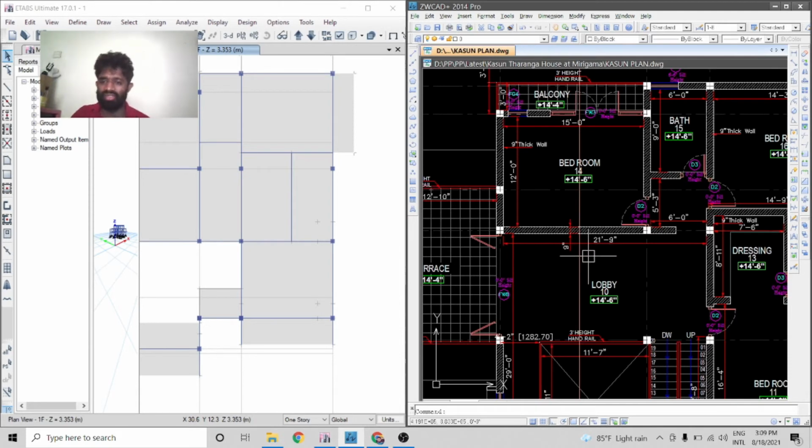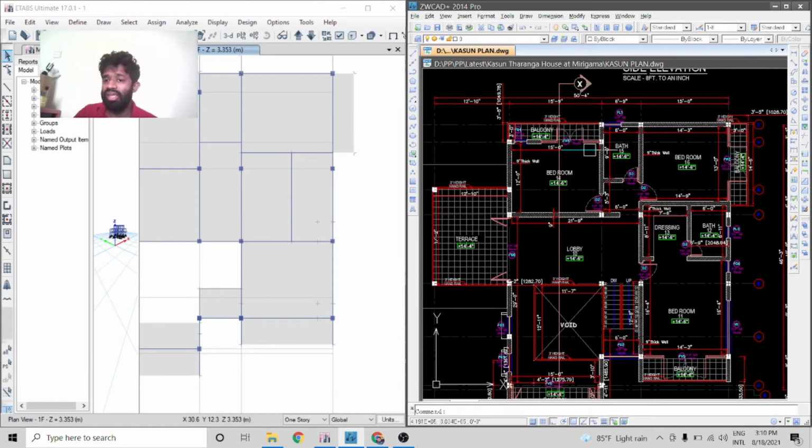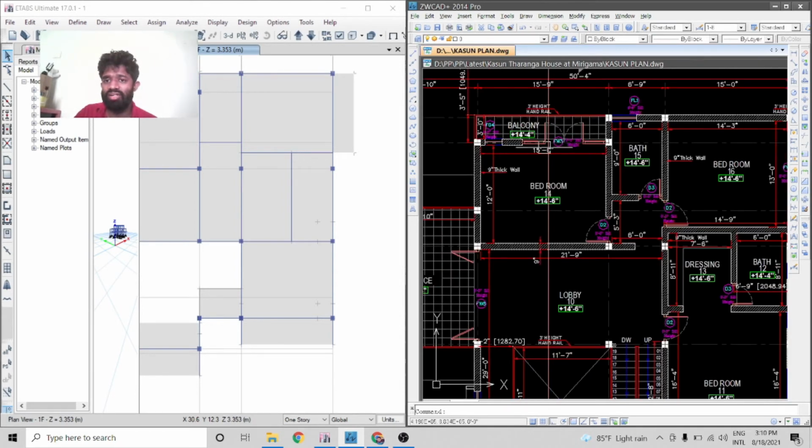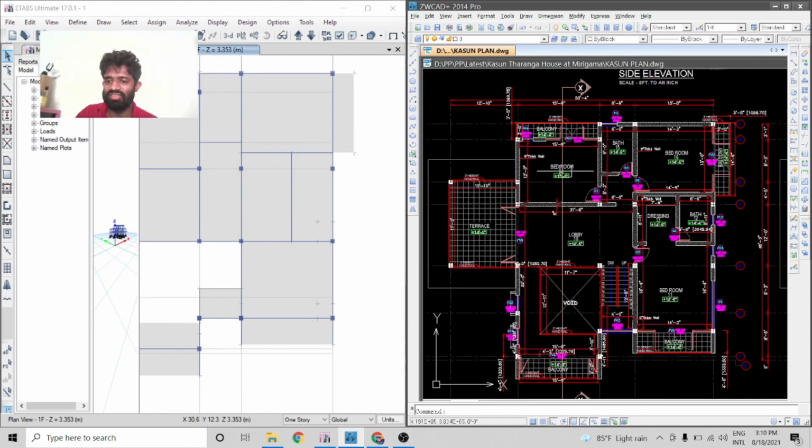So I have to calculate it. When I calculate the wall loads, 0.225 into 21 into, let's say the height is 3 meters, then we'll come up with 14.1. Let's use 14.1 load everywhere. If you like, you can reduce the wall loads in these door and window areas.